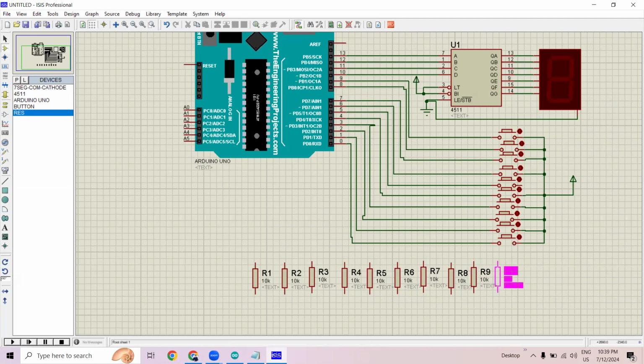In a few PCs, if you are facing the issue of duplicate part reference, that is because of how we drop the resistors. In my case, it's showing all the numbers like R1, R2, R3. In some cases, it's not necessary that it will show you all the numbers. So what it puts on the screen is R question mark, R question mark, R question mark, which means there are a lot of duplicates in your circuit.